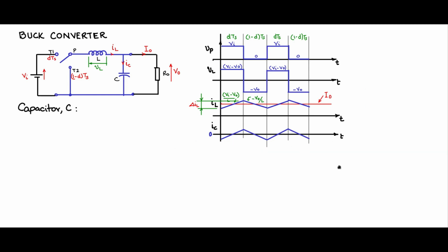So let us remove some parts of the waveform, focus on the capacitor current. Now let me shade this. This is the area under the capacitor current curve on the top, and this is the change in the charge. We'll call that one delta Q.